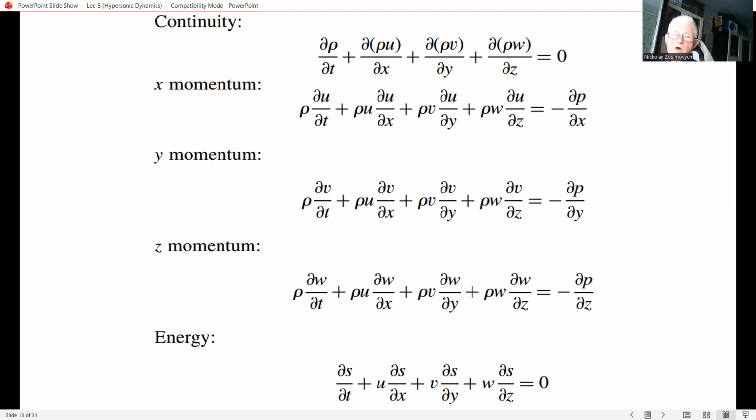The solution of the compatibility equation and the evolution of the characteristic directions are in general computed simultaneously as the solution procedure marches downstream from the initial data surface. In this manner, the entire supersonic and hypersonic inviscid flow field can be calculated, namely in the exact fashion.